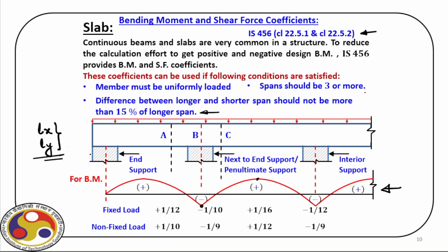So as you can see here, we have supports over which this slab spans. We can see that this support has some width, as also this support. So there is a dedicated clause. Depending upon the type of supports, we need to consider the center line, and that will tell us the effective dimension along this direction between these two supports.